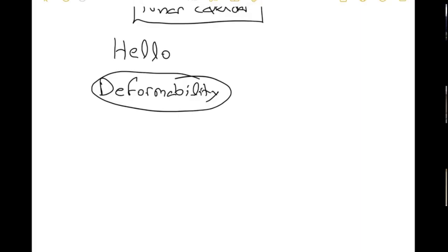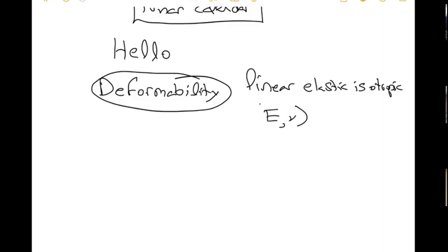And so if we use theory of elasticity, and we say that the material is linear elastic isotropic, which pretty much all materials are under small deformation. That's actually what Hooke figured out in 1685, from all sorts of experiments. And then theory of elasticity comes along and we say there are two parameters. And they can be expressed as Young's modulus and Poisson's ratio.